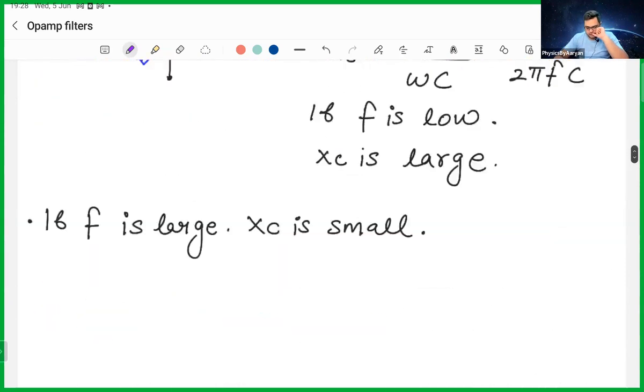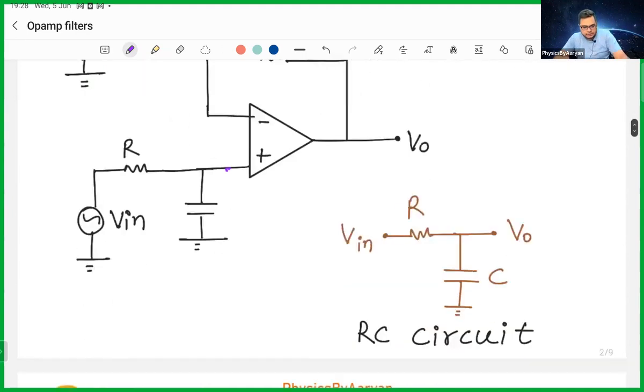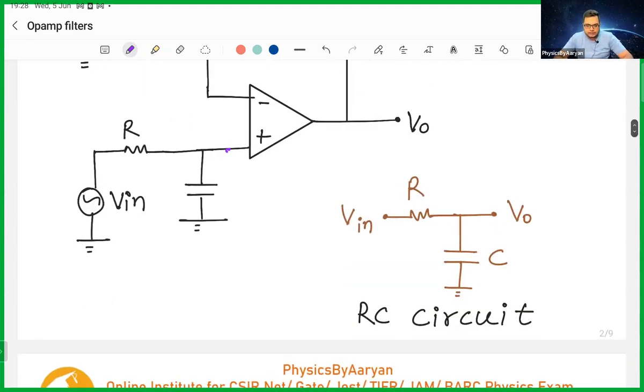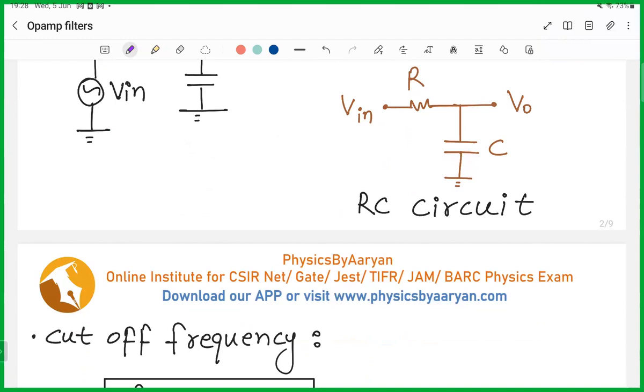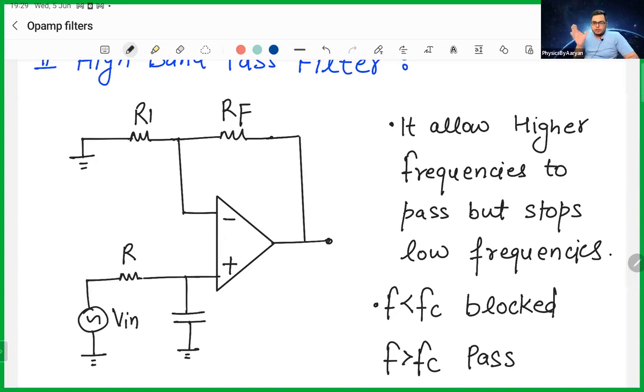Okay. And unfortunately, I made the same circuit. Sorry for my mistake. I think there will be a little bit of change here. Let me check my notes. A second. R and C will be switched. Right? Yeah, it should be switched. The only difference between low pass and high pass is that the entire rest of the circuit is the same. The capacitor will be replaced by a resistor, and the resistor will be replaced by a capacitor. And this becomes your high pass filter.